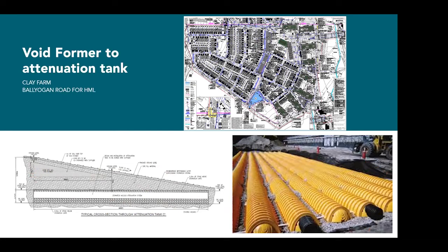So they came to us again. It's a similar thing. We need this kind of shape. We supplied the information, the compressive strength of the material. The engineer was able to work out, well, I need this density of material. Is it an EPS 70? Is it an EPS 100 that I need here in this location?